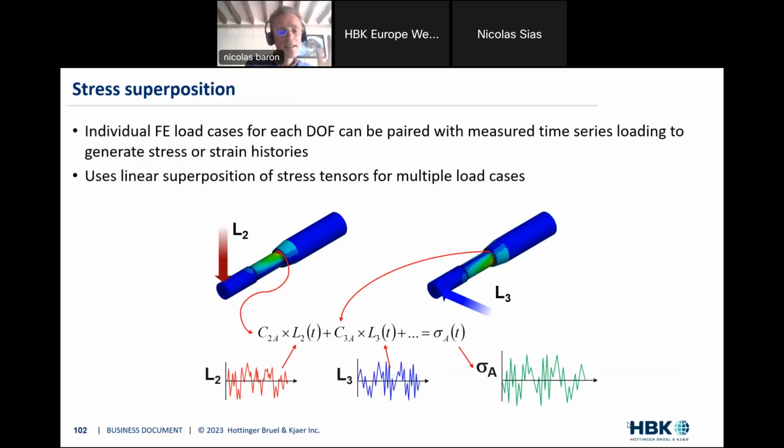And we have in Design Life the principle of stress superposition. So you can combine here. I had one loading in that example I just showed you, but you're not limited to that. You could have various loadings and you could combine them all within Design Life in a very straightforward manner to calculate your fatigue, having different load cases.